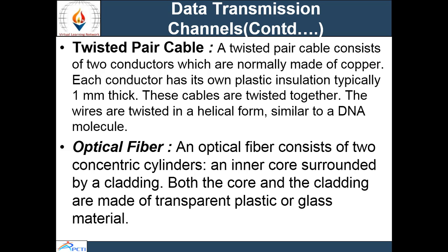The performance of the twisted pair can be substantially improved by adding a metallic shield around the wires. Shielded wires are much more resistant to thermal noise and crosstalk effects. Twisted pairs are used for long distance connections. Example, telephone line, which are usually organized as large cable containing numerous twisted pairs.